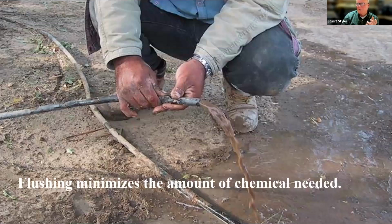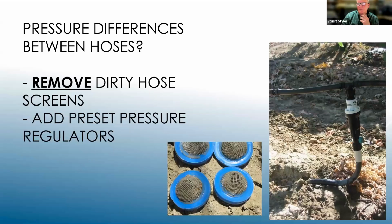But this is what we're really looking for. We're looking for those hose flushes to be flushing clean, or maybe to not run for more than about 20 or 30 seconds. If they run for 2 minutes or 5 minutes, we're not doing adequate flushing, and we're not doing adequate filtration out on the systems out there.